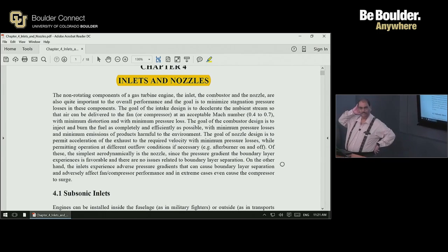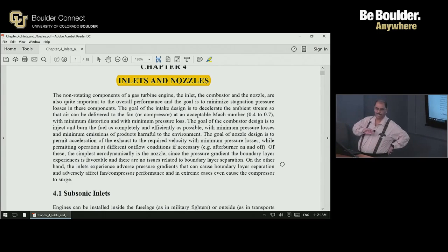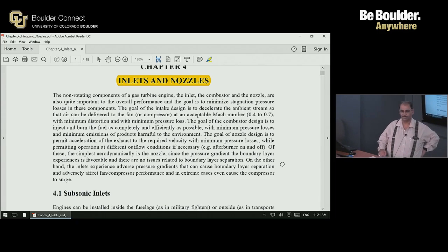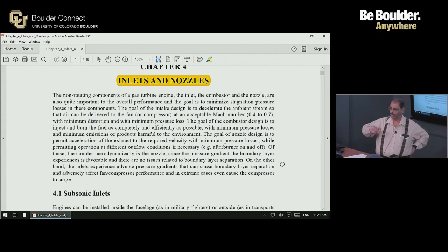Okay. The flow usually over the nacelle accelerates, since the cruise Mach number is 0.8 plus, typically 0.85, Boeing 747. The flow over the nacelle can accelerate locally to slightly beyond Mach number 1. Okay. When that happens, the deceleration on the back side at the rear of the nacelle usually involves shock waves.